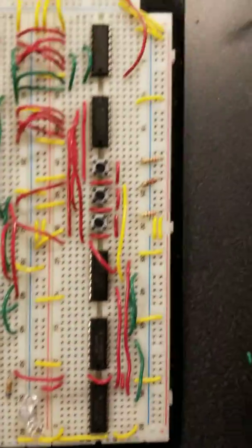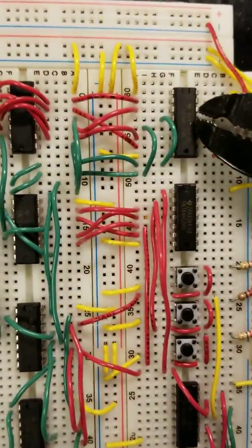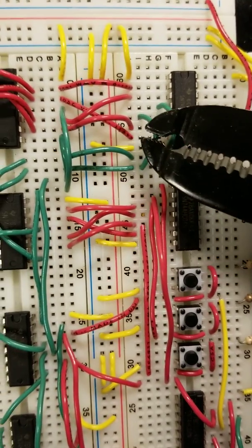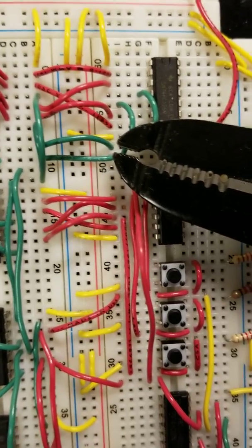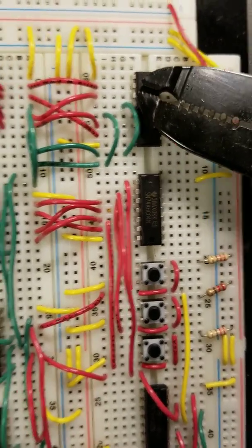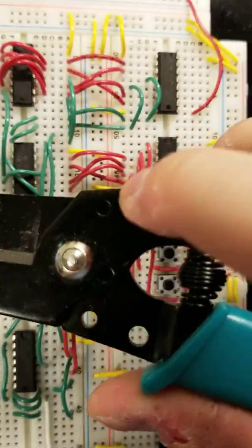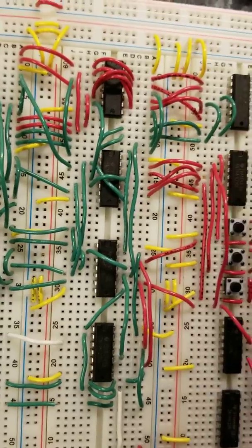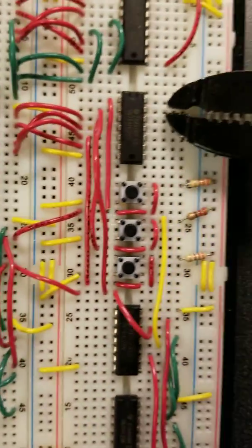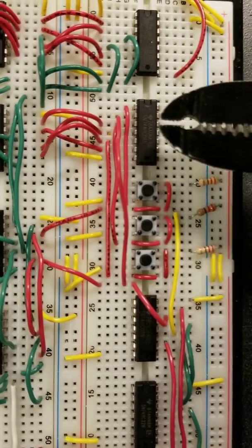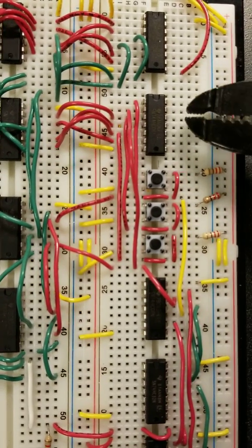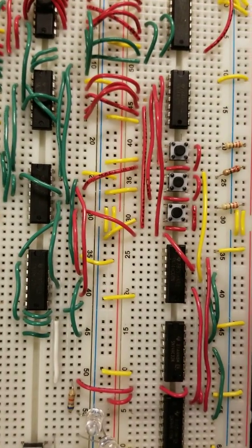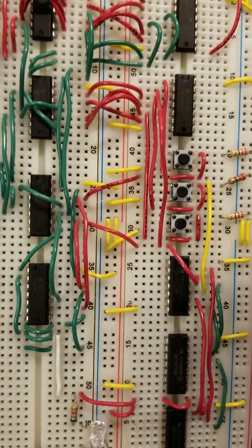Over here, we have the register with T1 and then T0 over here. And of course, the outputs of these registers will be plugged into the different AND and OR statements that are used to construct the next state. Further down, we have an inverter. This inverter is mainly to create the equations that were derived from the state transition diagram.